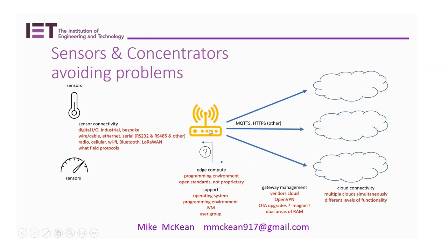You then mount operating system 2 into the device. If all goes well, great, that's how it runs. If it doesn't go well, you fall back to operating system 1 in RAM area 1. The important bit is you didn't try and do an upgrade and lose the device. It was intelligent enough to fall back to the other image. Right.